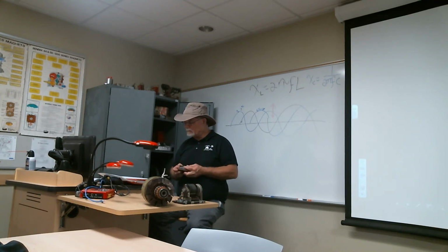Yeah, okay, there again some AC versus DC questions. And I'm not going to say that one is better than the other. They both have pros and cons. In general, AC is a lot more convenient, but they really suck when you have to use a battery. It just don't work. So you need to know what full field diagnosis is versus flashing the field to establish residual magnetism.